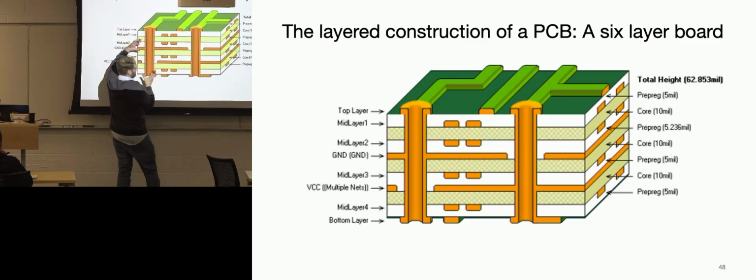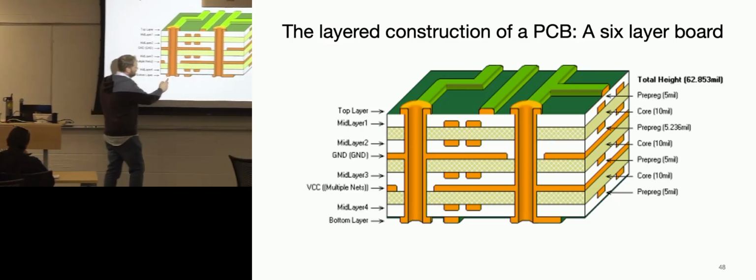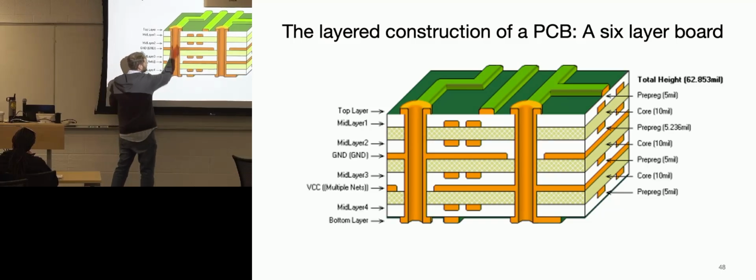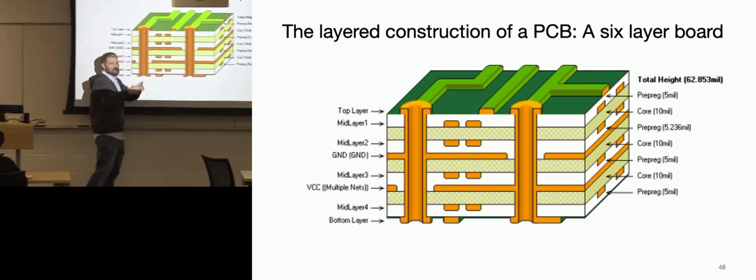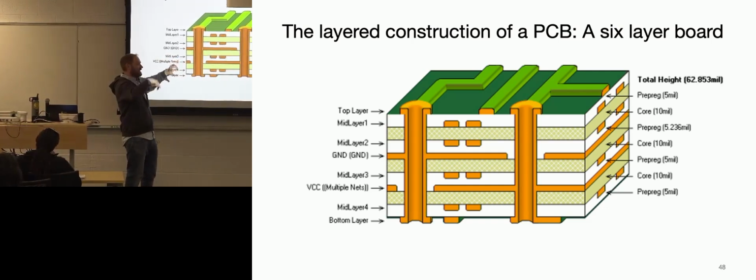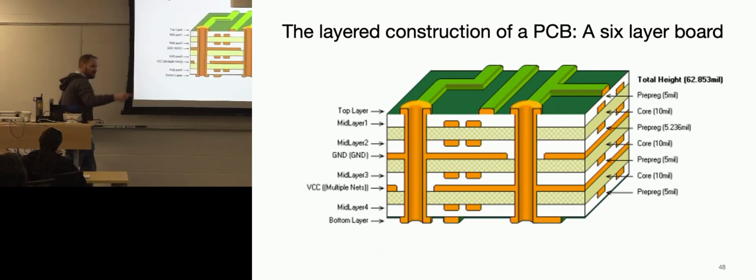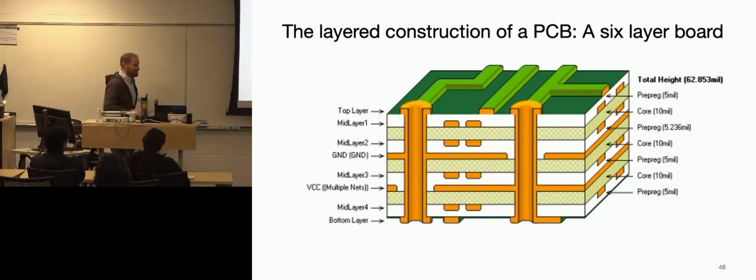And now the problem is that as all these boards come together, all these vias have to be aligned up. And this is actually a tricky process. And so what the manufacturer will tell you is, for a particular drill size, they want what's called an annular ring. You can kind of see part of that ring here. They have to have a size that's big enough. So imagine they're trying to hit a dartboard. I was not prepared. I went off on a tangent.